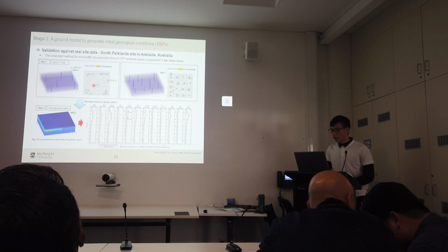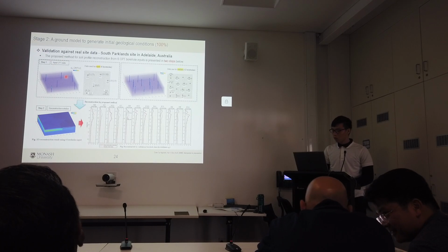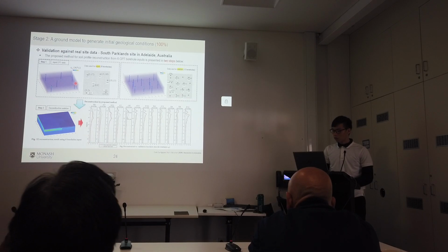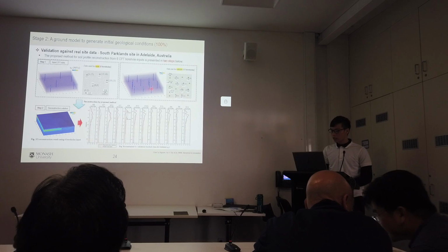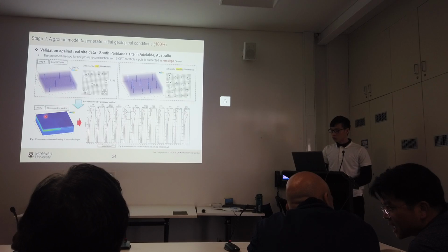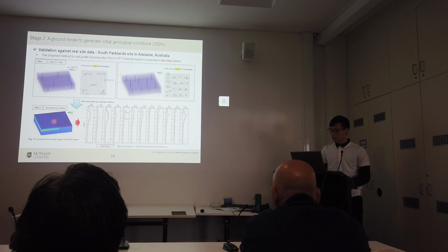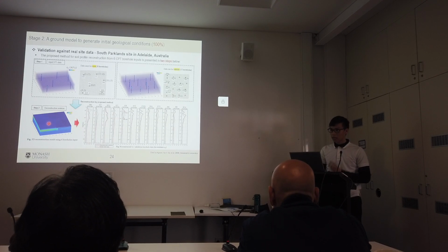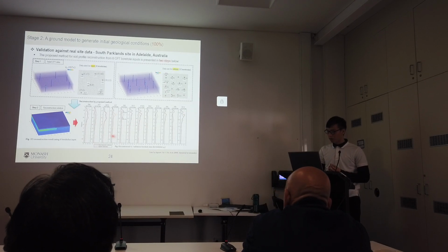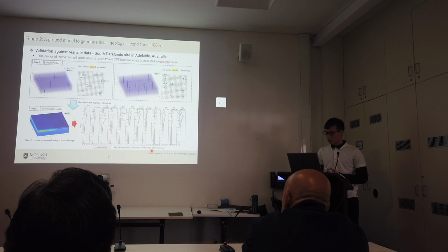Here's the model performance. We present the process in 2 steps. Step 1, on the left, we input the 6 CPT borehole data into 3D space. On the right, you can see the visualization of the 12 boreholes used for validation. Step 2, using the 6 borehole inputs, we apply our proposed method and then we can reconstruct the entire 3D soil map.